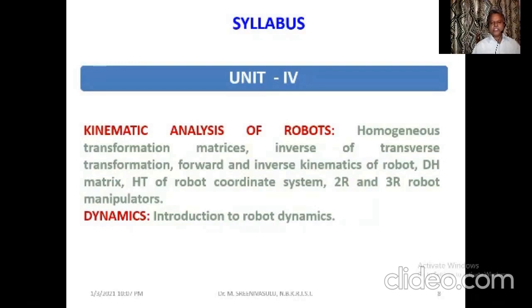Joint space to the Cartesian space transformation has been referred to as forward transformation. Reverse is actually being referred to as inverse transformation. For the sake of that, we shall try to take the support of homogeneous transformation matrix, and we try to apply the forward and inverse kinematics.